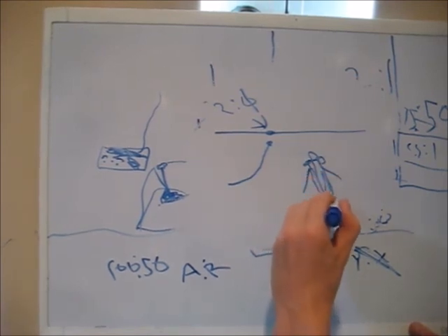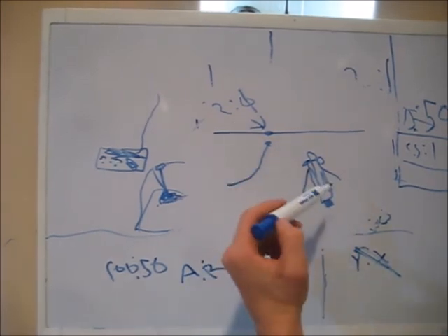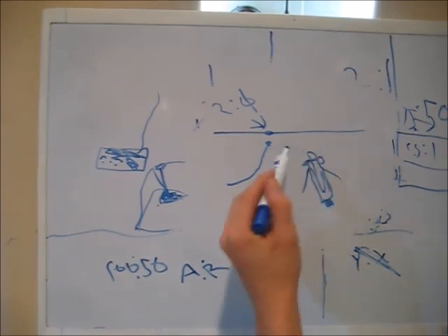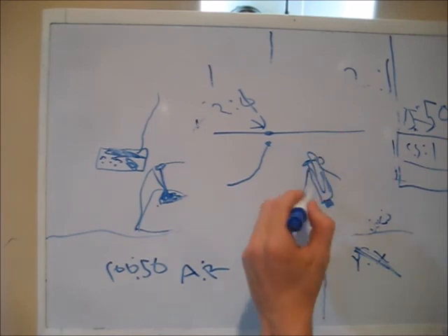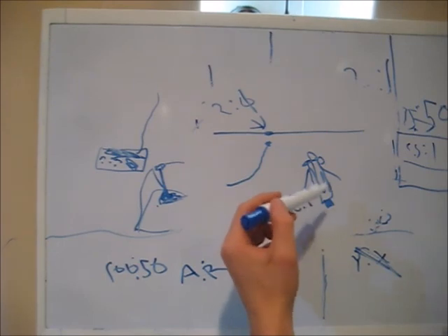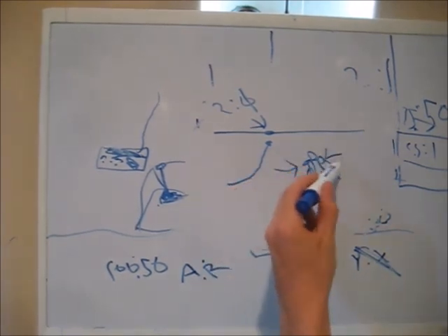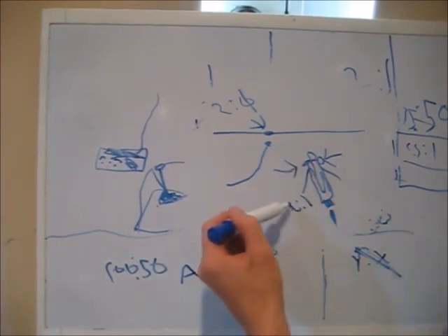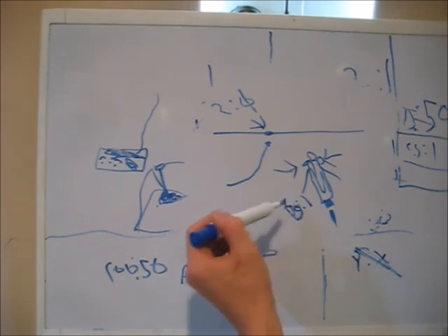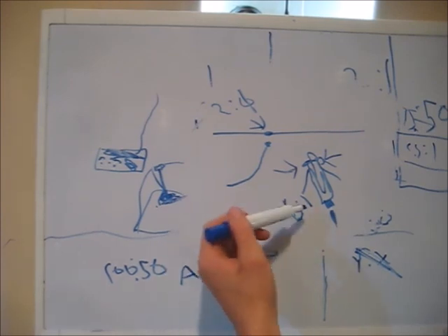They sell a balun. Now what a balun is, it divides impedance. The way baluns are rated is 1-to-1, 2-to-1, 4-to-1, 6-to-1, 9-to-1. So a 2-to-1 balun, don't be scared of it, because it doesn't mean it's going to have a 2-to-1 SWR. What that means is that if the incoming wires that you hook up to it have 100 ohms, it's going to downstep it to 50. A 6-to-1 would mean that it would take 300 ohms and convert it to 50. A 4-to-1 would be 200 ohms converted to 50.